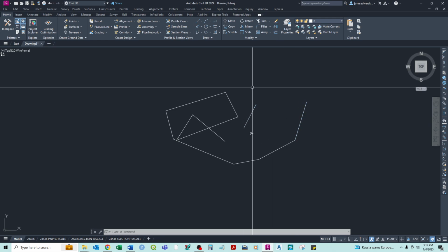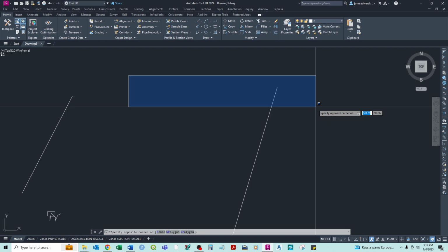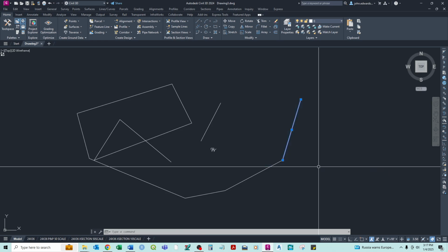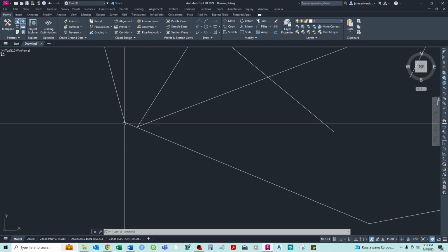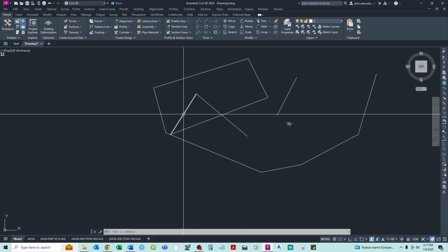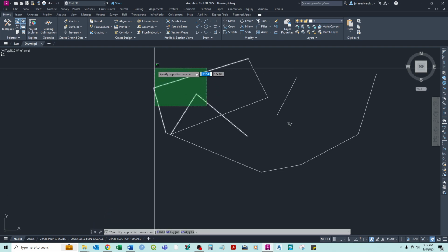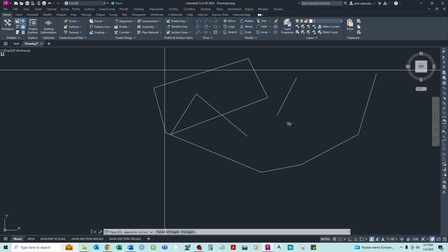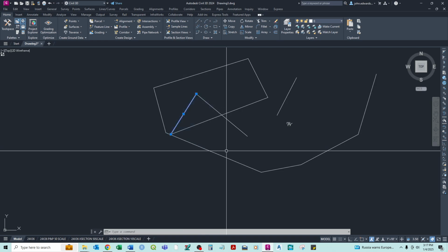Contrarily, if you drag to the right and you have this blue with the solid line, you see how it's not wanting to select it. If you do it this way, you have to get the entire object within the window before it selects. But where that is helpful is, say there's smaller features in here and it's hard to work around everything. If I was just trying to pick this line, you can easily accidentally pick other things. But if I start here and encompass this whole line, but it doesn't encompass any other line, I can select that specific line within there.